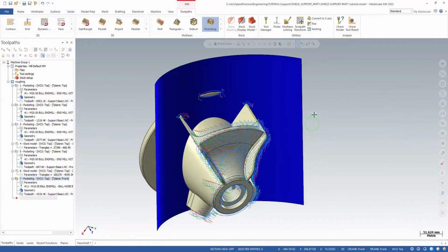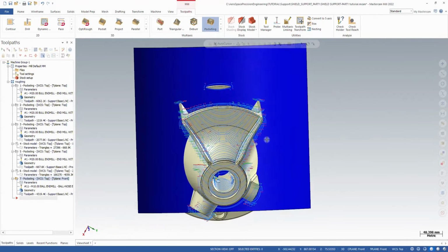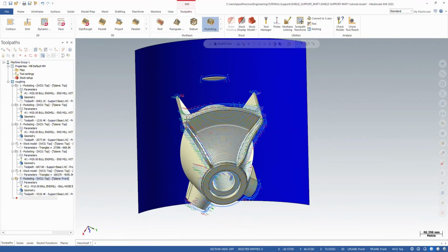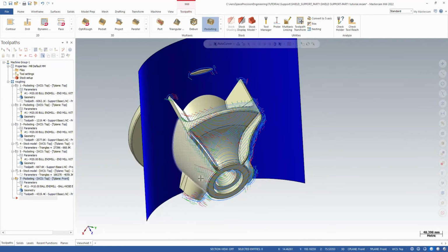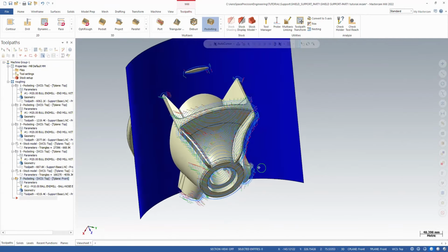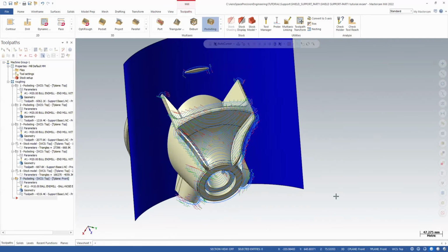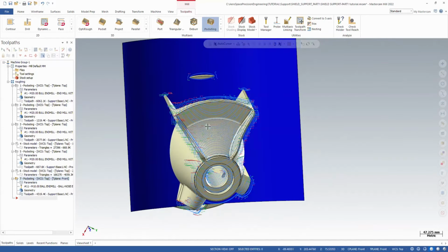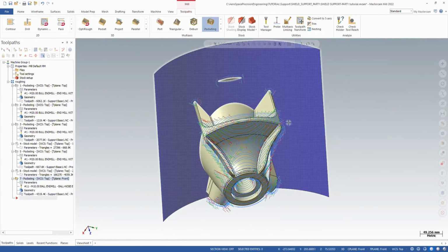Okay, so this is our toolpath. As you see, we went a bit farther than we wanted. We even plunged inside here. It is because Mastercam sees material everywhere, and we selected the whole 3D model as our machining surfaces. So I will use the containment boundary option inside the toolpath to limit the working area,